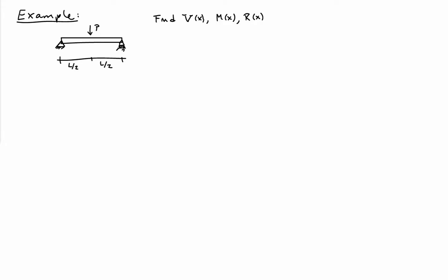As an application of our equilibrium expressions for the bending of beams, let's look at a simply supported beam with a point force in the middle. The force will have magnitude P, and it's located right in the center of the beam. It's a simply supported beam, and that means that it's pinned on the left side and it's sitting on a pin roller on the right side here.